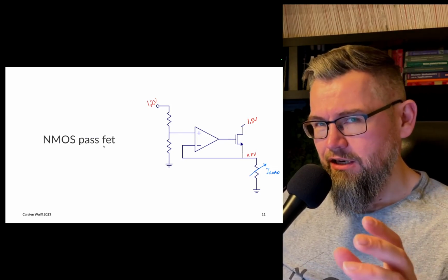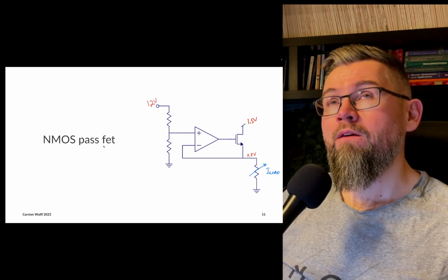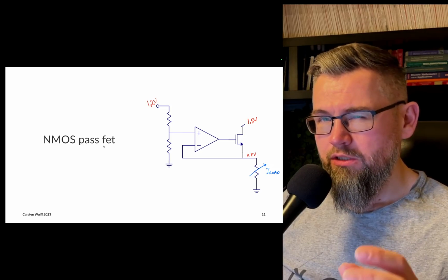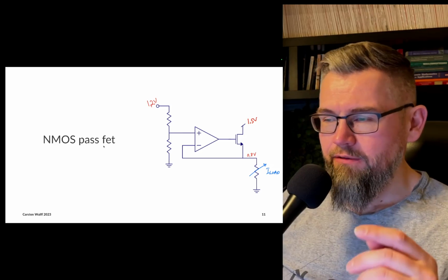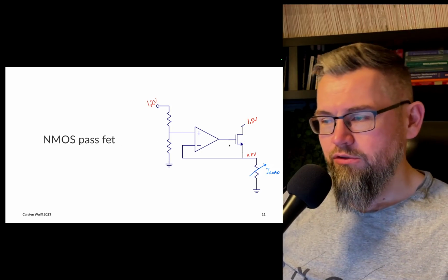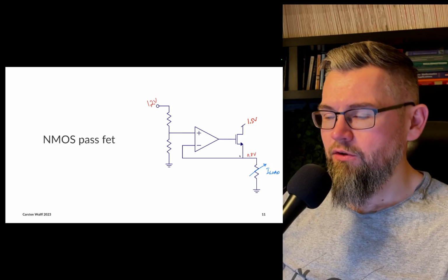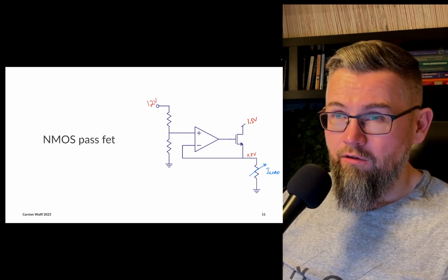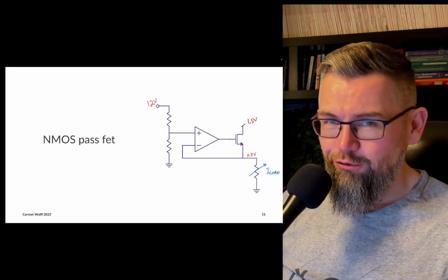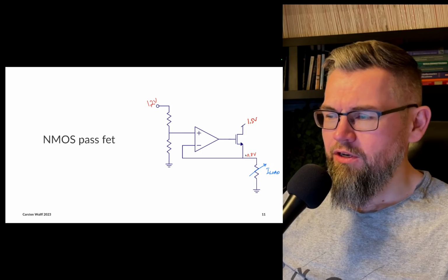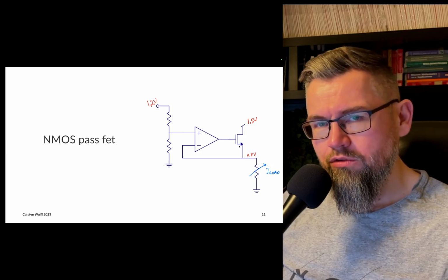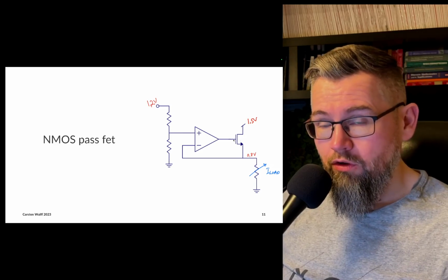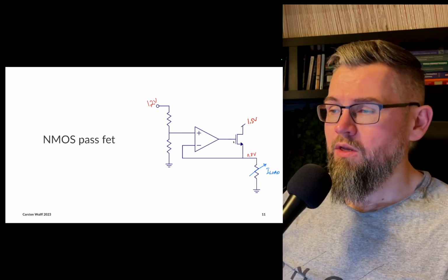There's a couple other reasons, and I'll direct you to the link in the syllabus that goes on LDOs, which I believe was from Razavi. Anyway, we can use a source follower instead. In this case, we get the same thing as sort of a voltage controlled current source, but we're using a source follower, which means that the impedance looking into the source of the NMOS is actually quite a bit lower. And we can deliver more current for a smaller device.